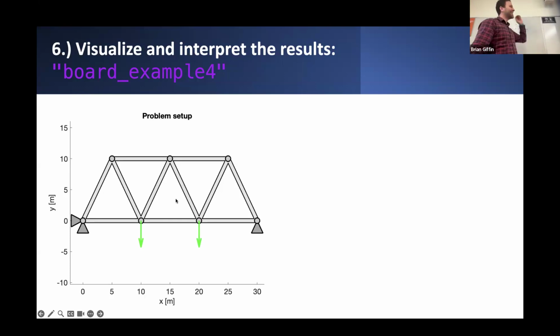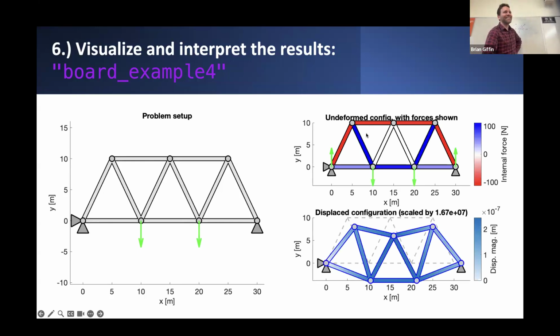Compression, tension. Intuitively, based on the previous examples, I would want to say tension, right? Just because that agrees with this joint moving down. It would seem like these are elongating, right? The answer will surprise you. They're zero. But why? Because the top is straight, so the forces are balancing on the top, and we don't need those extra branch.